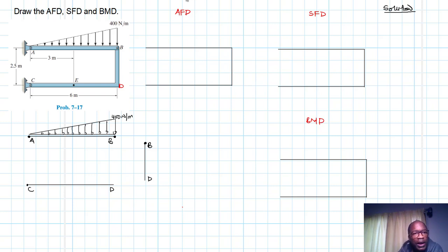So let's go to the page where we did this problem so that we look at the support reactions at A and C, and the internal forces at the joint B, as well as the internal forces at D, because we need to section this beam here and section it there, so that we have separate members, as shown here. We've separated all the members because we want the internal forces at the joint, the reaction forces at the supports A and C, as well as the internal force at the member that we've sectioned at D. Is that fine? Great. So let's get back and have a look.